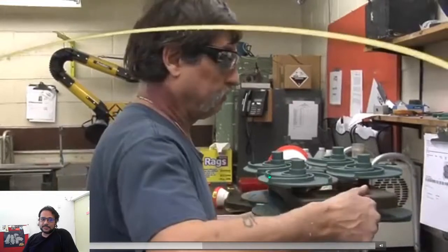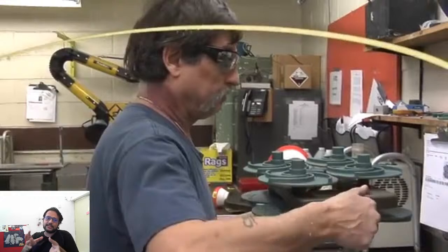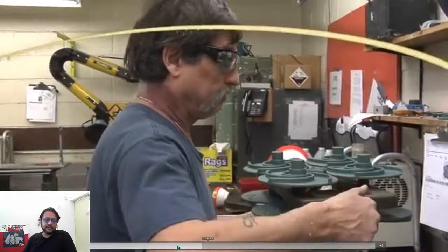As you can see in this piece, they are trying to cast these impeller blades for probably a pump or a blower. Once the wax pattern is made, they have assembled it onto this other piece of wax. This square piece is also wax. They've assembled it in a manner which resembles a tree, so that's why it's called a wax pattern tree. Okay, and let's move on.